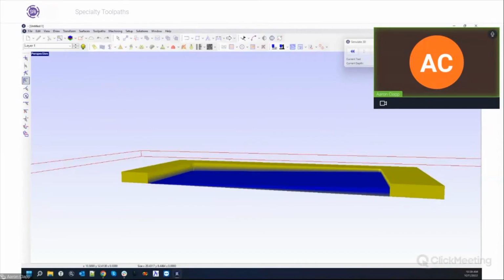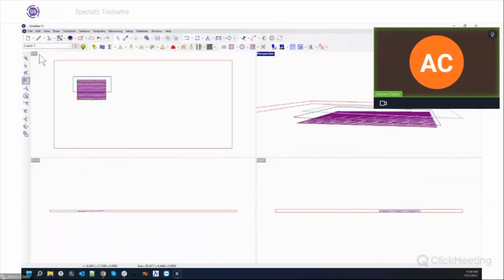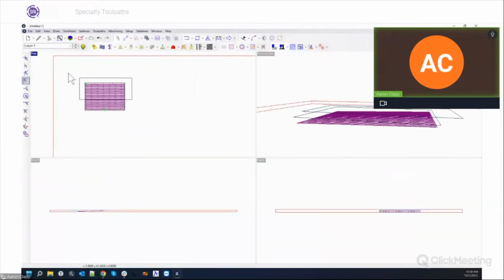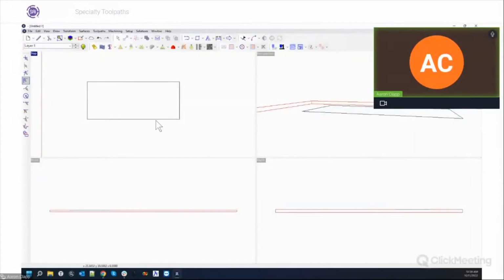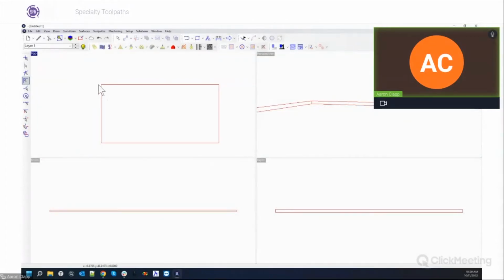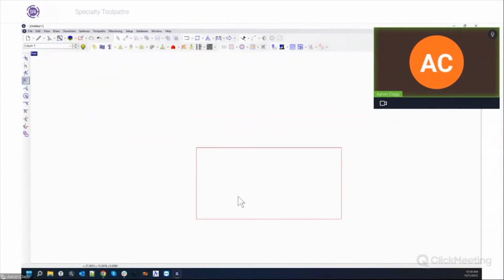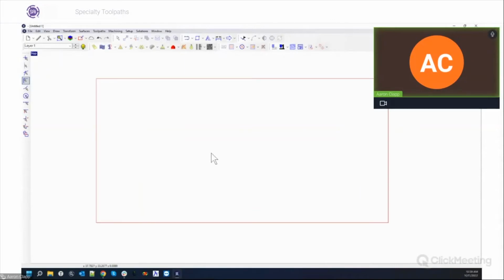And then I think we'll wrap up today with the option for slots. I kind of want to just mention this one again because I think it doesn't get used as often as maybe it should. But the slots toolpath is kind of a unique toolpath in that it allows you to do keyhole kind of toolpaths where you need to plunge in, move, and then retract out of the same location.